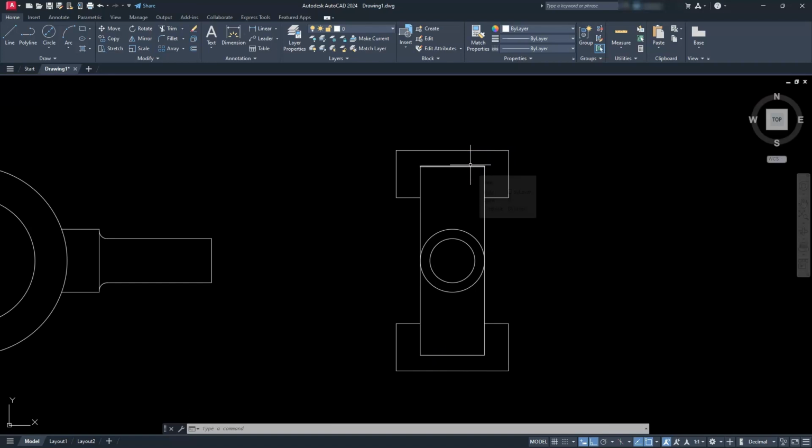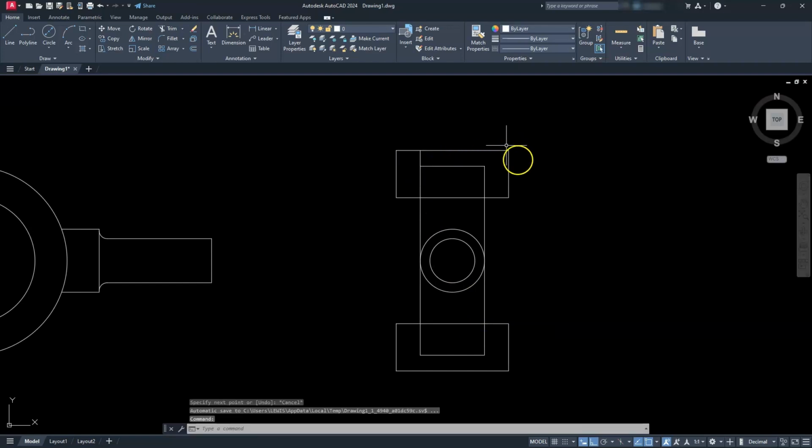Let's go ahead and finish by putting the rest of our hidden lines into here. So I'm just going to draw a line going right across here. Likewise going across here. I do have a couple more going up to here. I'm just hitting enter and escape to get out of the command, and then I'll go back and hit enter here. Click on that endpoint, come down, escape, hit enter, go from that endpoint, come down, and then hit escape. So that's my quick way of doing that.